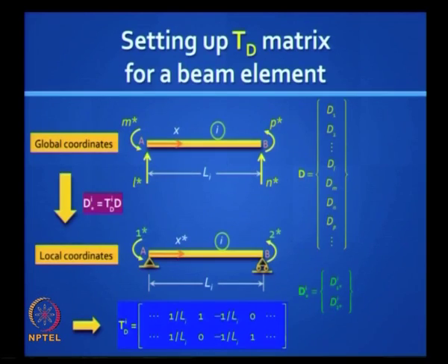You are also familiar with what you do for a continuous beam, and if you have chord rotations, relative support settlements, then you have to use this chord rotation which is given by 1 by L, and clockwise chord rotations are treated as negative, but the equivalent beam and flexural rotations which is 1 by L will turn out to be positive.